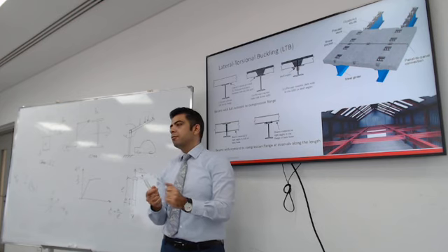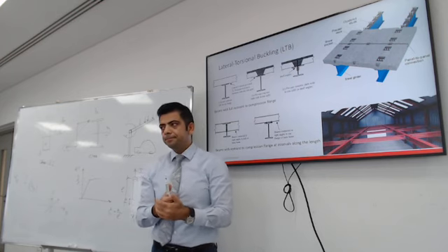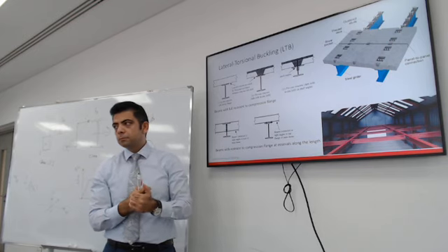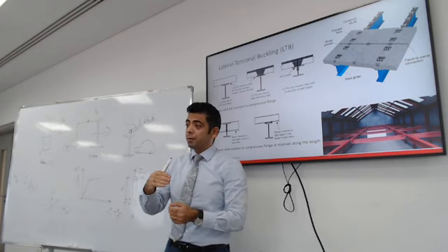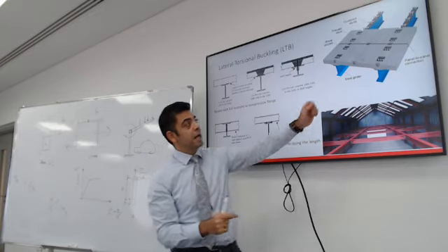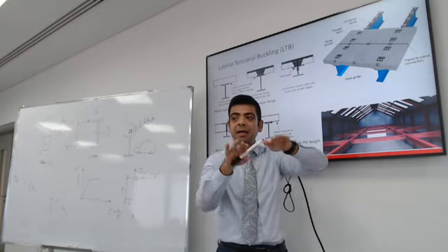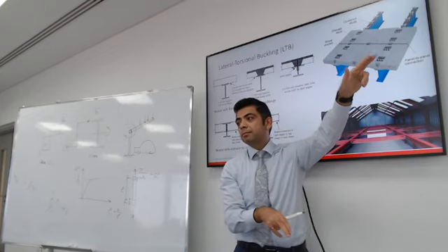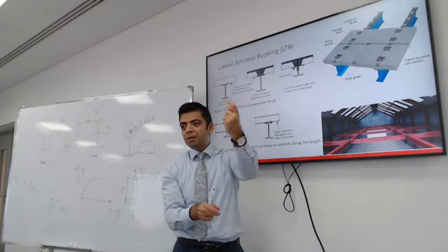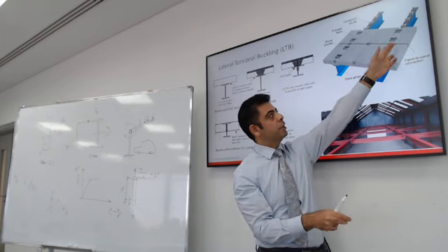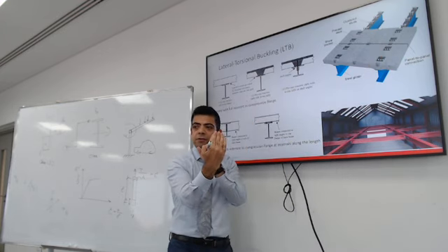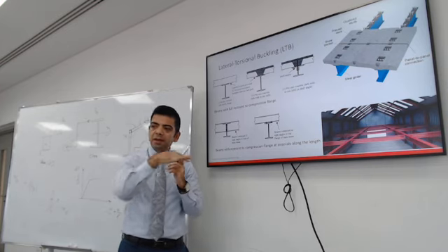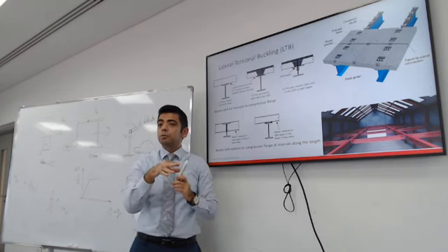So how do you design a beam for lateral torsion buckling? Make it a truss. Oh, you want to avoid lateral torsion buckling. Okay, the only way to avoid it is to make sure the beam is laterally braced all the way along the beam. The unsupported length is the distance between these connections. So you need to get these connections to be short enough so the beam doesn't buckle in lateral torsion buckling.